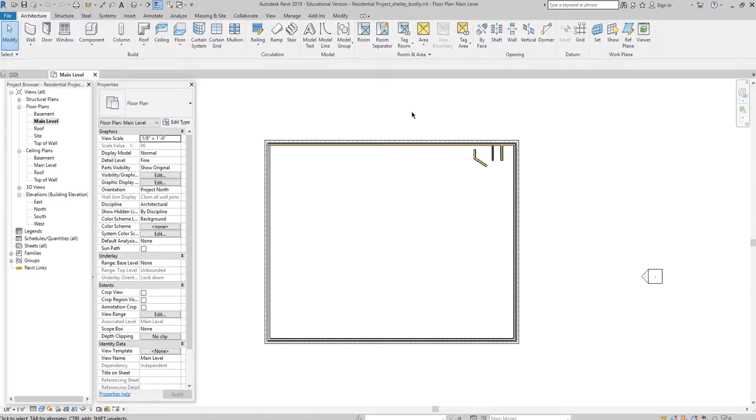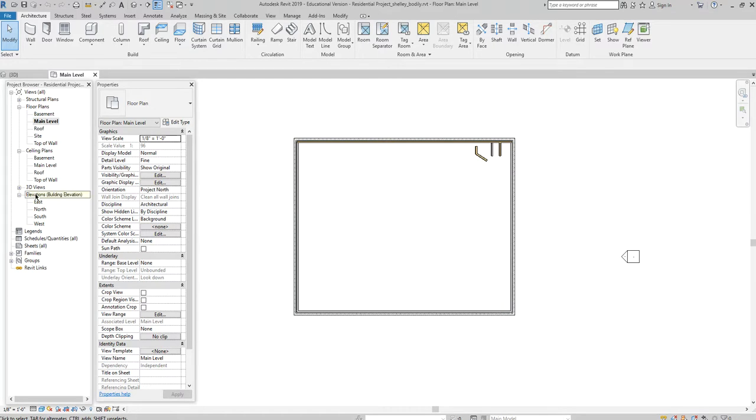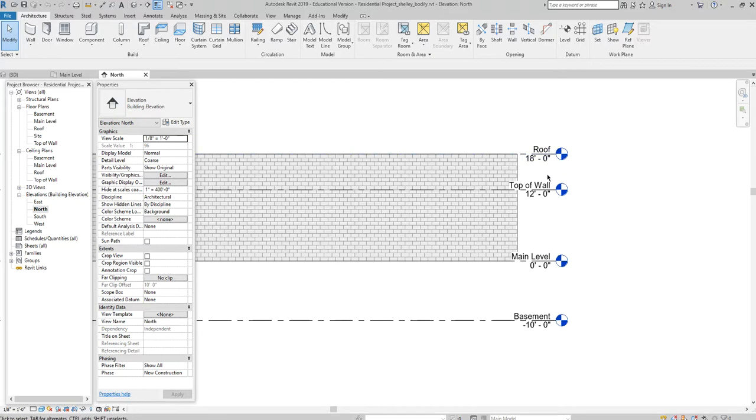Okay. So the first thing I want to remind you about with regards to walls is that our walls are tied to vertical definition in Revit. So that's the first thing I want to talk about, right? I'm going to go to an elevation view over here, and I want to remind you about our levels. Everybody feel pretty confident about creating levels? Good. Okay. So these levels define our model vertically, and it doesn't matter if it's in a positive manner upwards or in a negative manner downwards, like a basement. But they do define our models vertically.